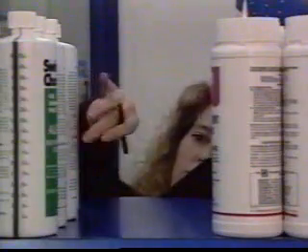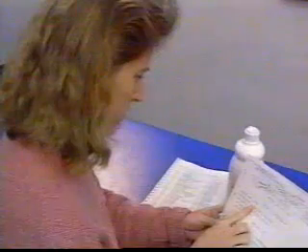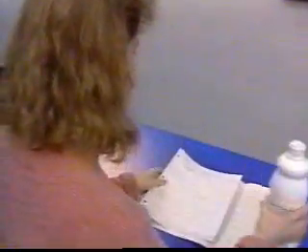When you notice a new hazardous chemical in your work area, see if it's been added to the inventory. The chemical name on the inventory should be the same name as the chemical name on the container label and on the MSDS. If the chemical isn't listed, or if you can't find its MSDS, let your supervisor know. Also, be on the alert for overlooked chemicals. Areas such as hard-to-reach shelves often contain hazardous chemicals, some of which are no longer in use. Tell your supervisor if you find any questionable items.